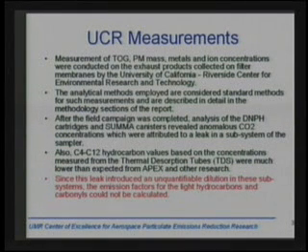I think the important thing to point out is that the analytical methods employed here and the sample gathering methods employed here were considered standard methods for such measurements. And so nobody anticipated that this actual part of the project would fail. This was probably the most straightforward. The hardest part here would be to ensure that we could get enough mass on the samples. We knew from the mass-based emission indices from Apex 1 what typically we could gather in terms of mass at a given engine operating condition. And that helped us to define how long we would stay on a test point and how long they were able to grab samples.